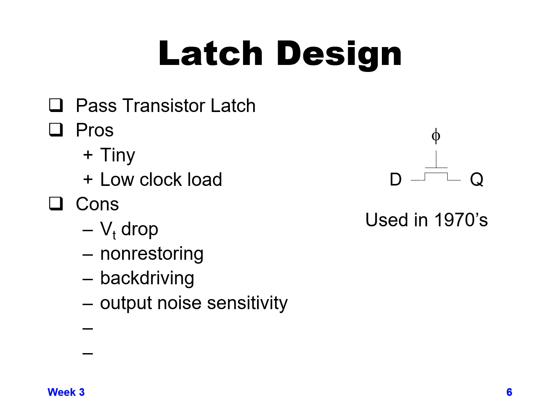It's also sensitive to output noise. So when, for example, you turn this latch off, so the clock turns off and turns that transistor off, if there's some sort of noise source that puts some noise on the Q, you're no longer driving it at all. It's completely undriven. And so any noise source on Q will just directly go on Q. It won't get overridden and pull the value back to either a 1 or a 0 like you would want.